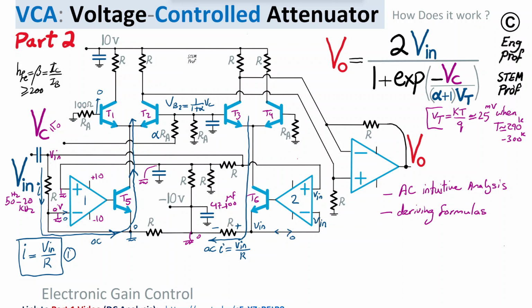So basically, the AC current is adding to the DC current, and the overall current for this pair is increasing, while for the other pair it is decreasing, in the situation when Vin is a positive voltage. Of course, when Vin becomes negative, the directions shown will be reversed. Okay, so with that in mind, the same idea happens here.